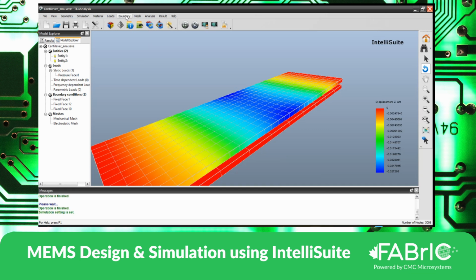It's a little tricky simulation because the applied voltage should not be in the range of pull-in voltage at all, because the device has to snap down only due to the applied pressure and not due to electrostatic force. So electrostatic force becomes a very sensitive parameter in the case of a capacitive type of MEMS pressure sensor.